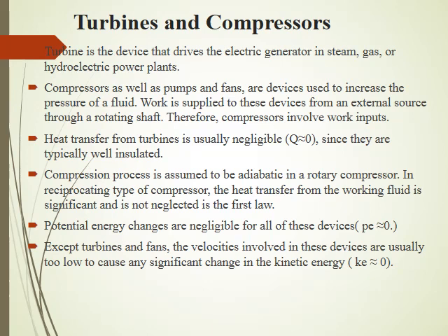In the second set of blades, the moving blades, this high velocity fluid stream is directed on a set of rotating blades, in which the velocity is reduced before being discharged from the passage. What is happening in the moving blades stage? There is a change of angular momentum because of the change of direction of the fluid, as well as the change in magnitude of velocity.